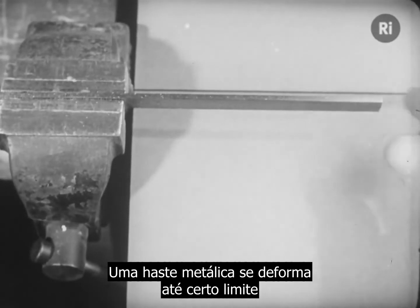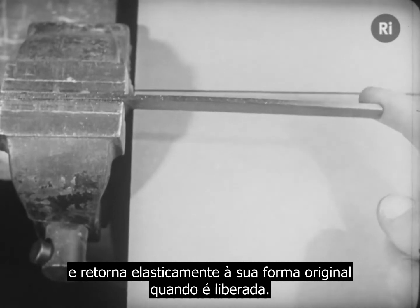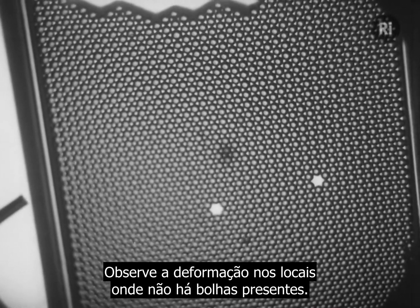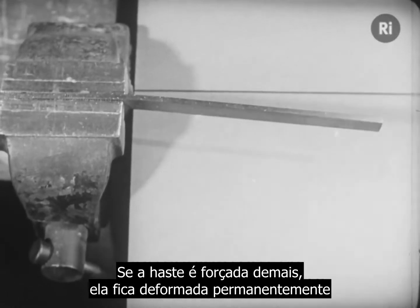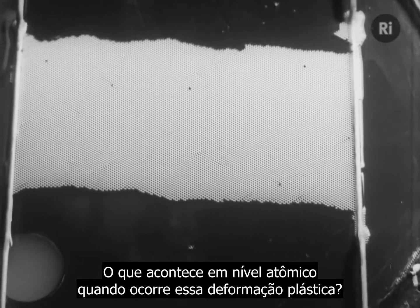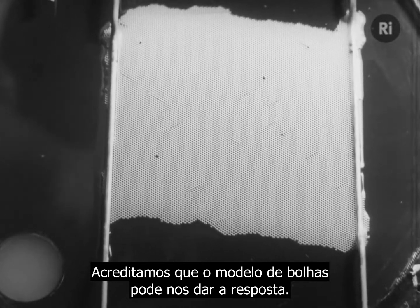A metal rod, deformed to a limited extent, springs back elastically to its original shape when released. The same is true of a raft of bubbles. Note this deformation at the places where bubbles are missing. If the rod is pushed too far, it gets a permanent deformation and does not come completely back. What happens on the atomic scale when this plastic deformation takes place? We believe that the bubble model supplies the answer.